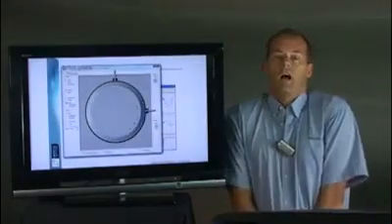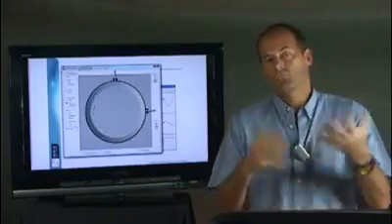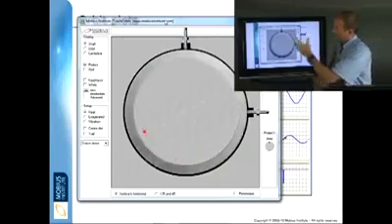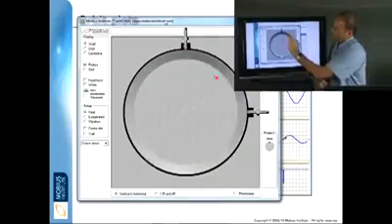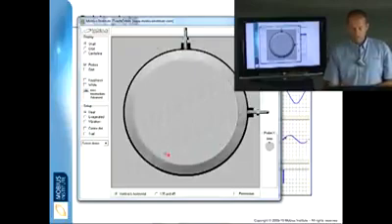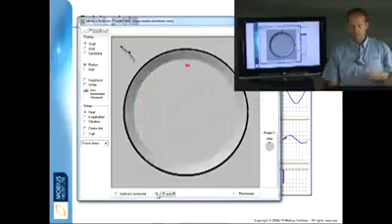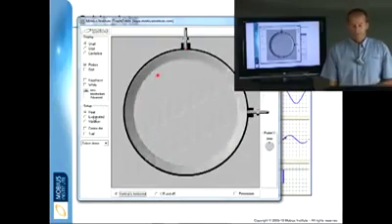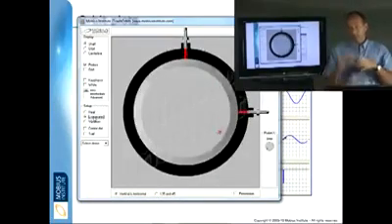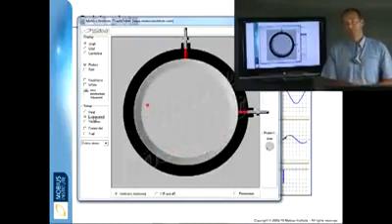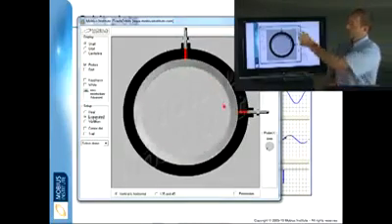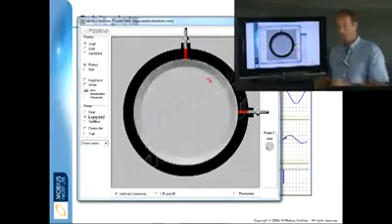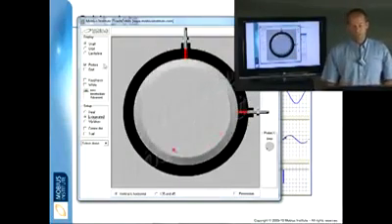So this is just supposed to simulate what's going on inside that journal bearing. So here is my shaft, and I've got my two proximity probes located in these two locations. As I mentioned, they might actually be located in different positions, but we'll just leave them there. What I'm going to do is exaggerate the size of that gap so that we can get some movement going and see what's going on. But basically, these sensors are able to detect the distance between the tip and the surface of that shaft.